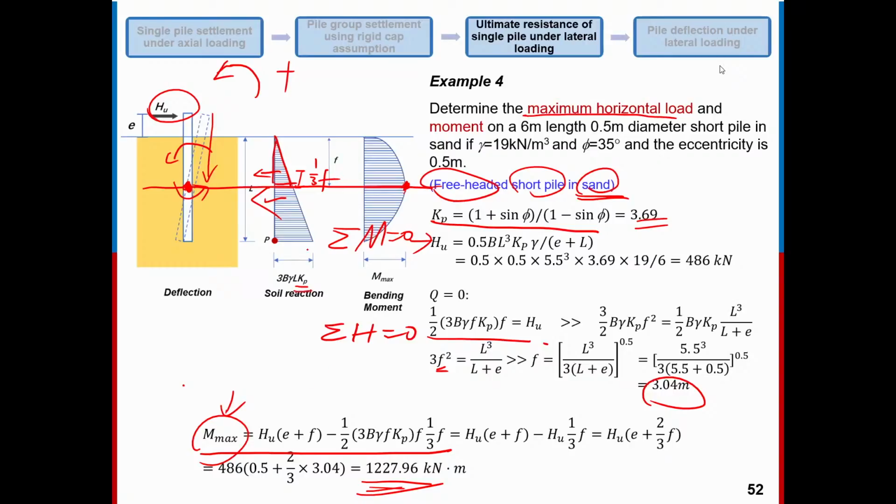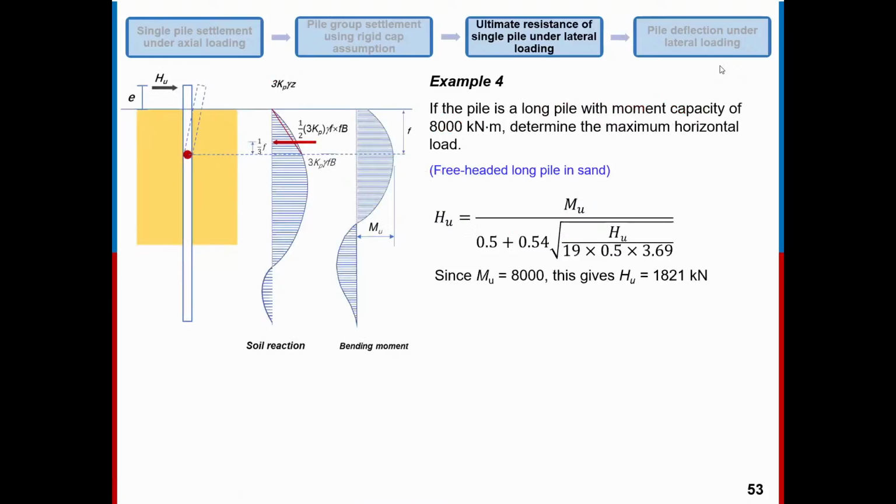So this is three things we normally do: equilibrium of moment, equilibrium of horizontal force, and the cutting. Cut it to two parts, and then we take a moment, or we just set the equilibrium of horizontal force. So we may say like this. Sometimes we just cut it first, and then we establish these two equations.